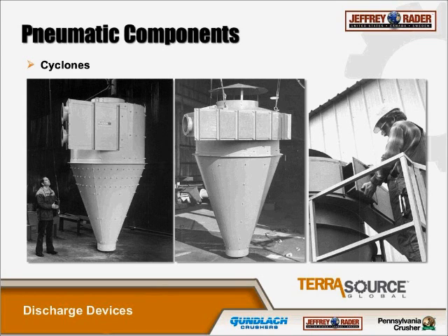So the way this works is that the air-to-material mixture enters a cyclone, then it spirals around the body of the cyclone very quickly, but the velocity is going to decrease because of the friction. Material is held against the sidewalls while the air begins to move inward. Material keeps on slowing down until it reaches the bottom, and it drops out in a spiral motion out that discharge port. Air does the same thing, though it moves closer and closer inward, tighter and tighter spirals, and when it hits the bottom, instead of going out, it shoots up the top and out that center top hat that is shown best in the center picture, or just releases the air to atmosphere.